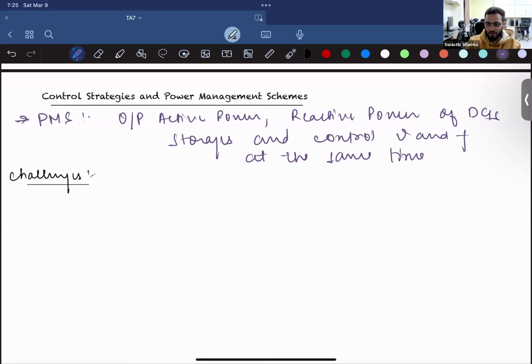But now you tell me, for a hybrid microgrid, can you have a global variable where you can track? So for AC microgrid, you had four different global variables, right? Your voltage, frequency, power, and reactive power. For DC microgrid, there were only two: active power and your voltage. But now here you have two different kinds of grids.